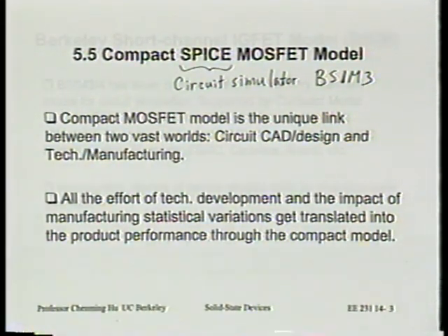All right. Okay. Now, another thing I will say, so this is called a compact model because there are other ways of representing the transistors, such as solving electron hole diffusion and drift. And that's not a very practical way of simulating circuits, not practical at all. Whereas a compact model will represent the transistor behavior by a very long analytical equation. It's very long. If you print it out, it probably will be 20 pages long, this equation. All right? But it is a compact model by the standard of computer simulation. Right? So we're going to talk about the compact model.